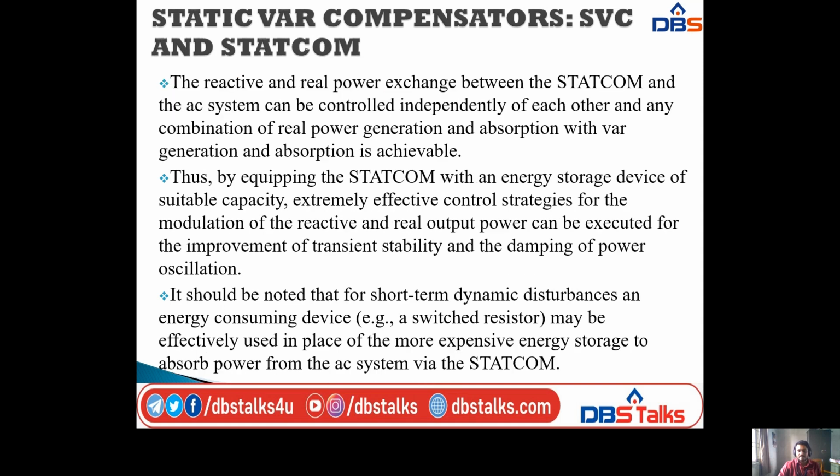And next, the reactive and real power exchange between the STATCOM and the AC system can be controlled independently of each other, and any combination of real power generation and absorption with VAR generation and absorption is achievable. So here I am taking both power exchanges, that is real and reactive power exchange between the STATCOM and AC system.